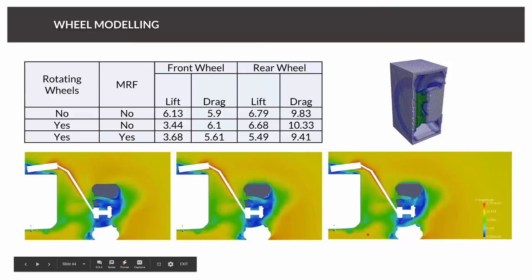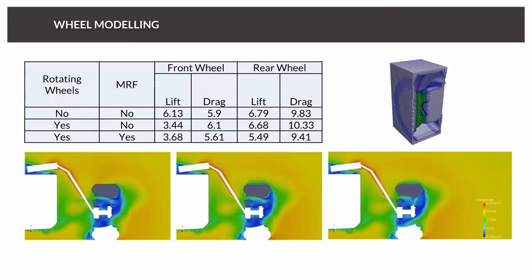And another point which is very important is what we call wheel modeling. If you think about it, in reality it's not like the air is streaming around your car, but your car is driving through the air. So it means that our wheels and the car itself have a relative velocity compared to the floor. And there are 2 effects we need to model.